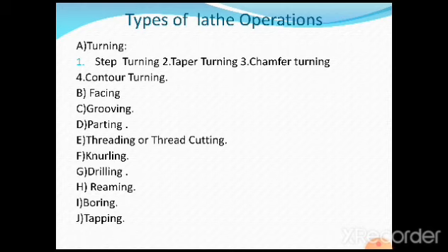And the second important operation is facing, third one is grooving, fourth is parting or parting off, fifth is threading or thread cutting, sixth is knurling, seventh is drilling, eighth is reaming, ninth is boring, and the 10th one is tapping. So there are nearly 10 major operations.